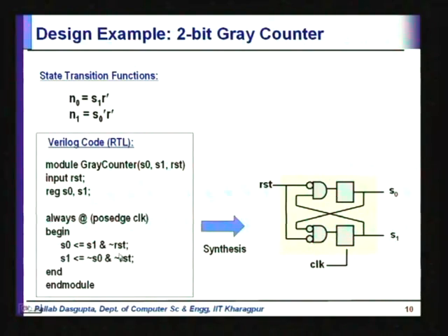So, the design is entered at this level and is output by the CAD tools at the circuit level. So, it can produce it at the gate level, at the transistor level, okay. And finally, when you have actually completely laid it out, it is going to produce what is called the GDS2 format, which then goes directly into the fabrication system, okay.